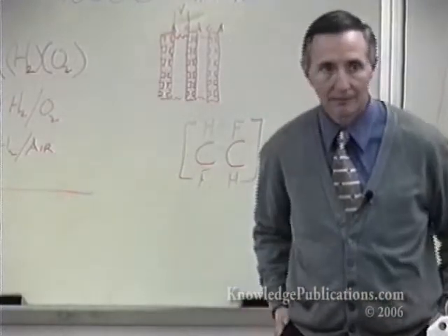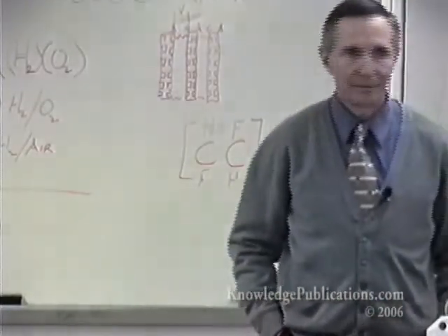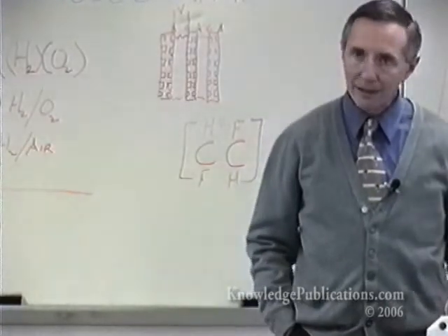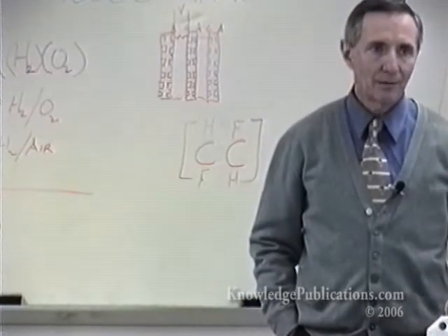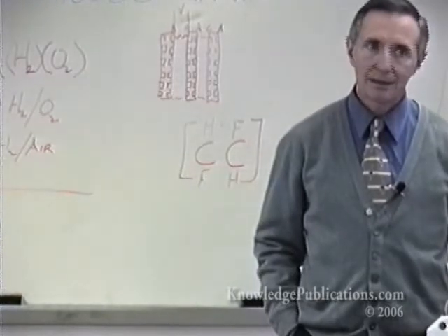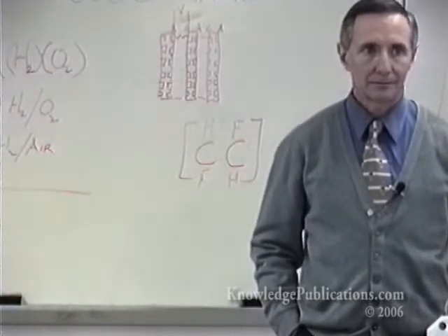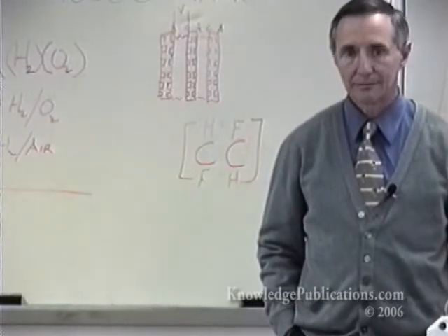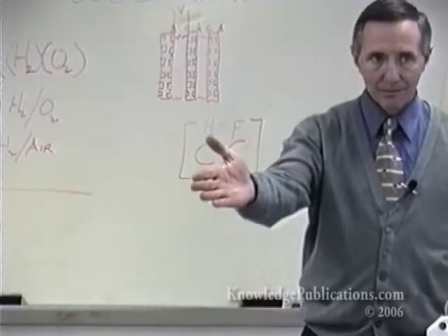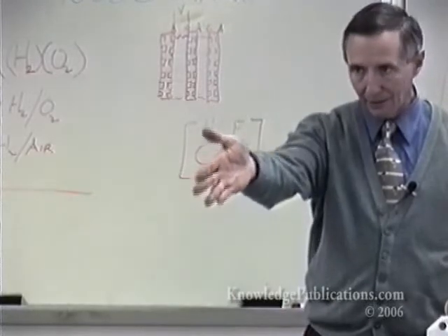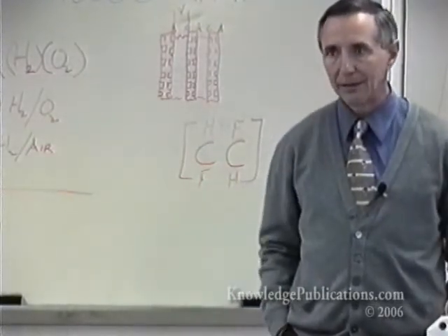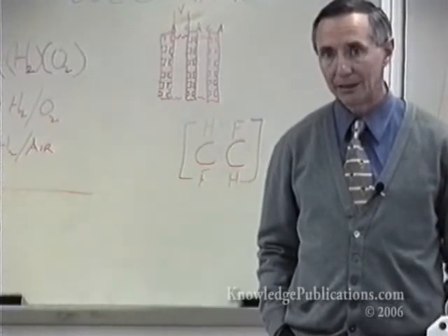In other words, it's not going to use any of that up? No. It's just a one-time loading factor? It's a one-time loading factor, and it's very susceptible to taking it all apart and recycling it. This one recycles very nicely. Now, with the phosphoric acid system, you do have to change out the stacks about every 6 to 7 years. But even so, once you've changed them, they are recoverable. The platinum is still there. It may be blinded, but it's still there.